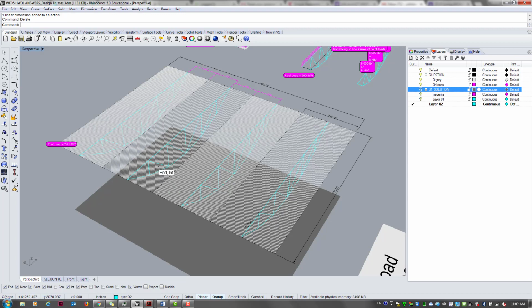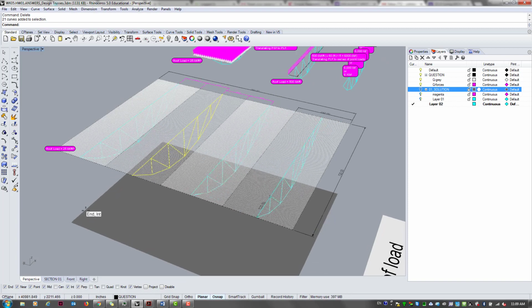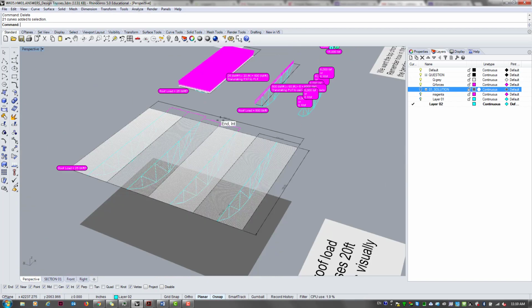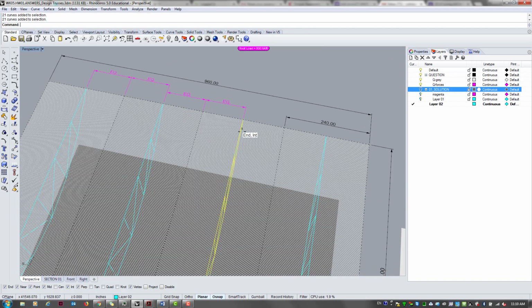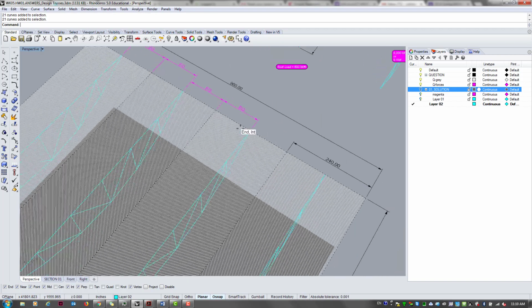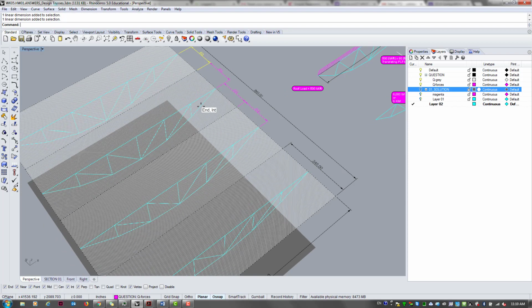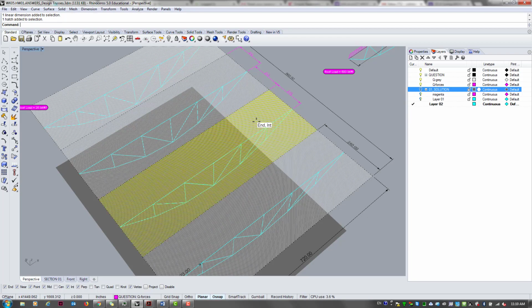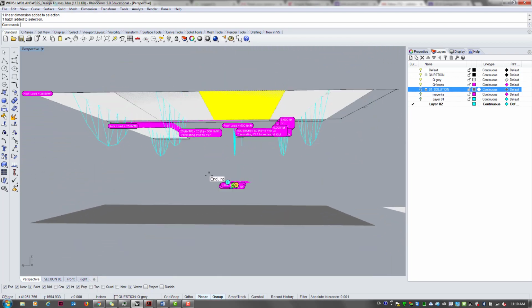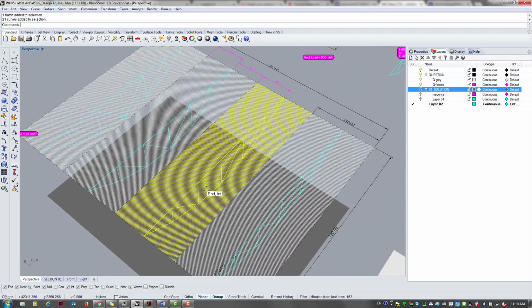basically how much of this roof slab each of these trusses is carrying the load to, right? So if there are 4 of them, they have to be distributing the work. How to determine the tributary area? It's simply by determining the midpoint between the two trusses. So you take the equal distance, that's the boundary. You take the equal distance to the next truss, that's the boundary. So for example, if you take that one hatch, that's the portion that's being taken care of by that one truss. Does that make sense?